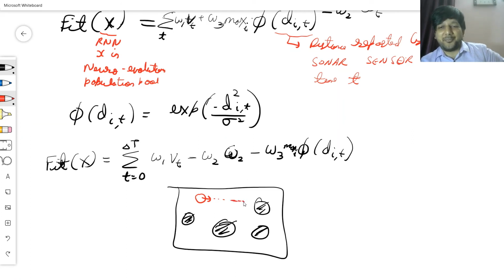However, when I come over here, then I need to learn that if I try to maximize the linear speed, this term becomes very large very quick. So I don't want to maximize my linear speed, because the penalty due to this will be very large. So I will maximize my angular speed. I know it's bad, but this bad is okay because it eliminates me from this extremely bad.